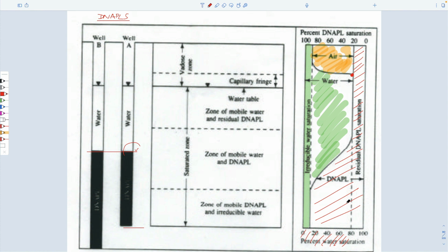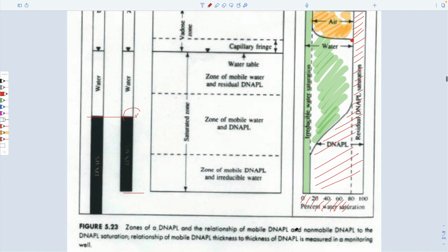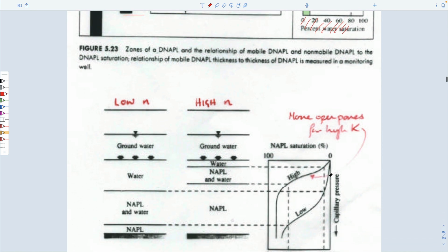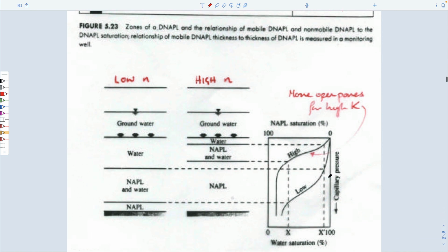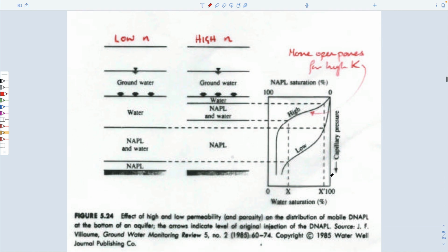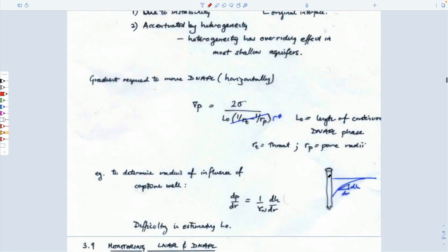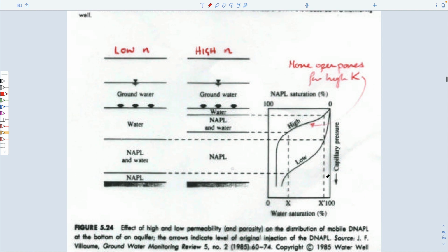If we blow liquid through here, we'll move free product only that will recover, and the water will be immobile. And we can rationalize all those mechanisms based on what we know about capillary pressure diagrams, the form of the saturation, and our knowledge of relative permeabilities, I suppose.